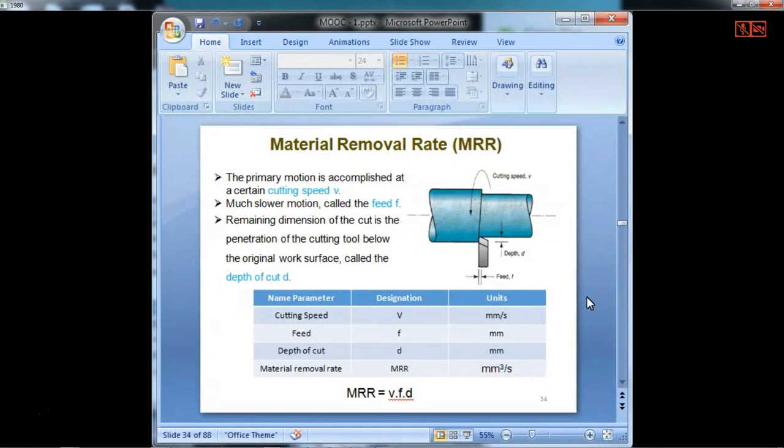Thus, to increase the material removal rate, initially we do the coarse cut where a large amount of material is removed. When you are close to the required dimension and want the finishing cut, a small depth of cut will be given, and then high rotational speed, and you can achieve a very good finish. And when you are making these calculations, the aspects I have said are important.